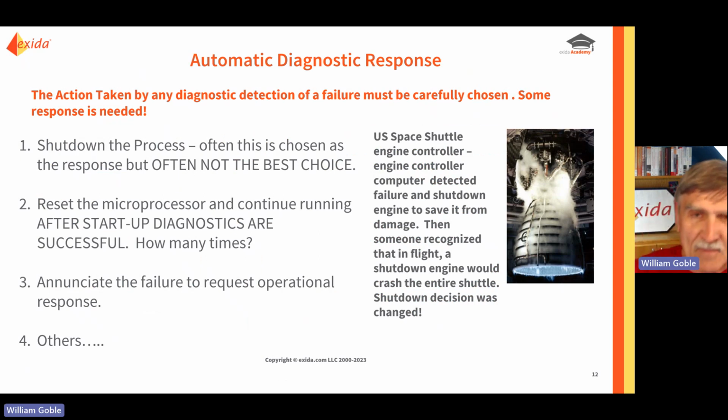Let's take a look at automatic diagnostic response. Automatic diagnostics are a great thing. Many think it's the future of functional safety. The main way to achieve functional safety is with automatic diagnostics, in the view of many. Well, what happens when the automatic diagnostic detects a failure inside of a device? A common solution is to shut down the process, in other words, take the output of the device to its safe state.